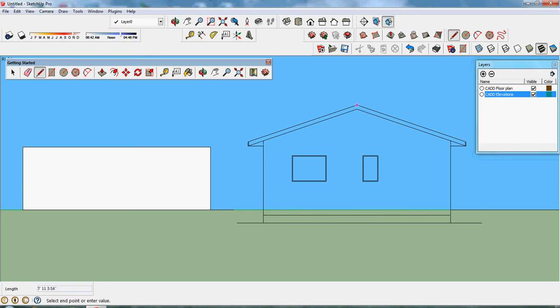So the pencil tool from the top roof to the end, to the fascia, to the soffit, back up, middle, back down here, again to the soffit and the fascia, and then when I touch this little top ridge, it'll close in and color. Now I've created a plate that I'm going to extrude.